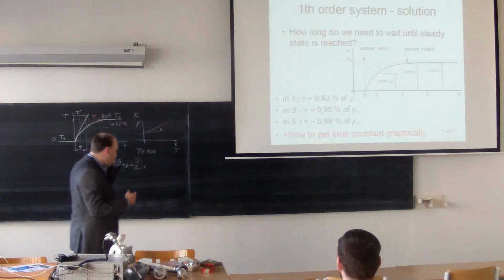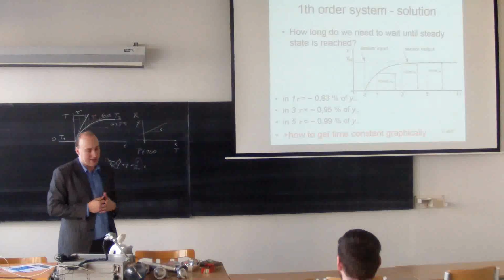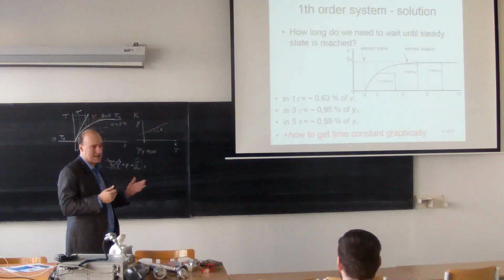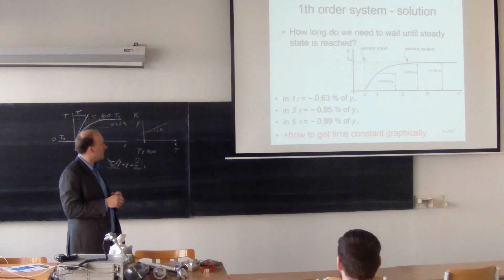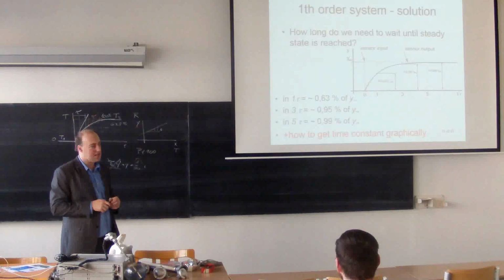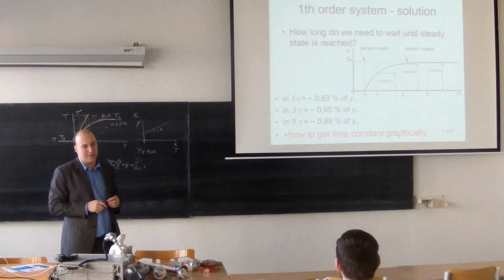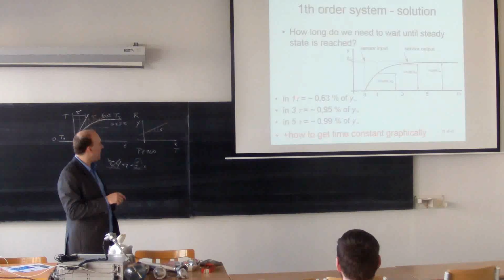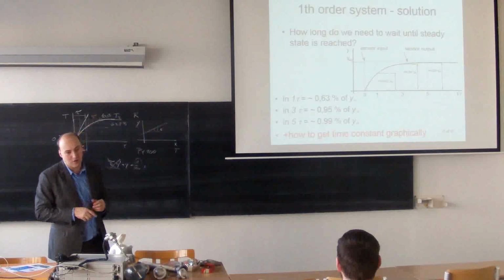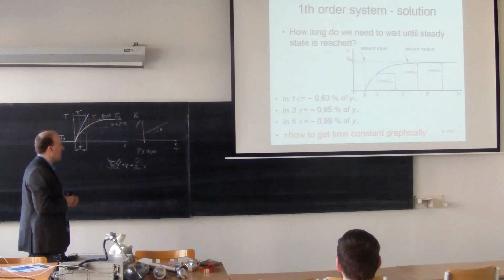So once again, let me repeat, how long does it take until the new steady state? Well, it takes infinite time, but in practical terms, if I wait 5 time constants, I'm within 99%. If I wait only 3 time constants, I'm within 95%. And if I wait only 1 time constant, I'm within 63% of the new value.